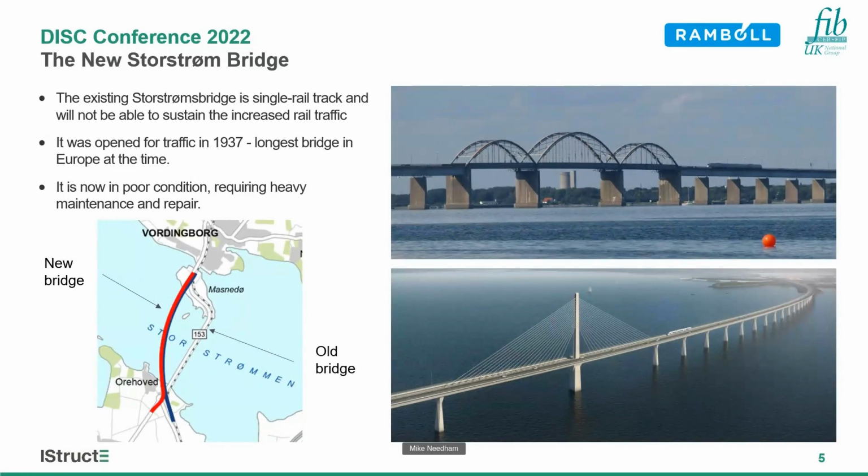The new bridge is going to be the third largest bridge in Denmark. It's 4 kilometres long, a combined high-speed rail and road bridge, and an important part of the Trans-European network infrastructure. It'll be one of very few bridges in the world that carry a 2-track high-speed railway as well as a 2-lane road and a combined footway and cycle path all on one single cross-section. There'll be 44 viaduct spans, 2 navigational spans, and the main bridge will be a cable-stayed structure with a 121-metre tall pylon.